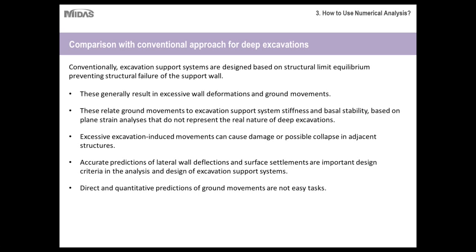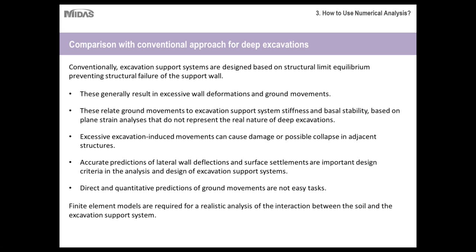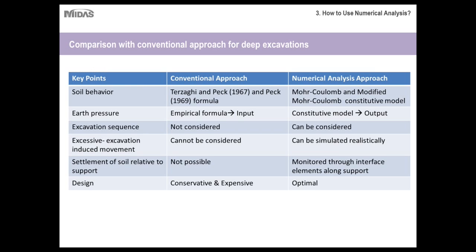Direct and quantitative prediction of ground movements is not an easy task. They are not simple, straightforward formulations that you can take from books and use for design when you're dealing with deep excavations. Therefore, finite element models or numerical analysis are required for a realistic study of the interactions between the soil and the excavation support system.